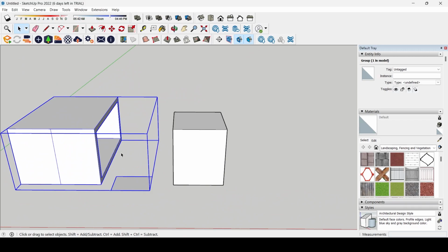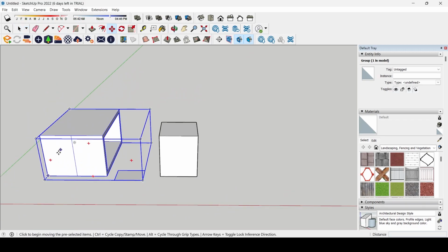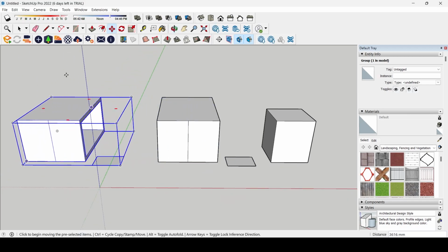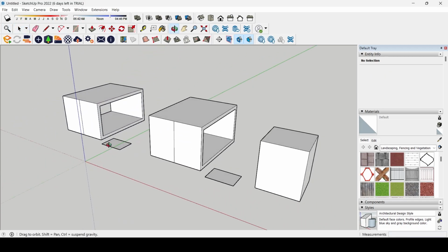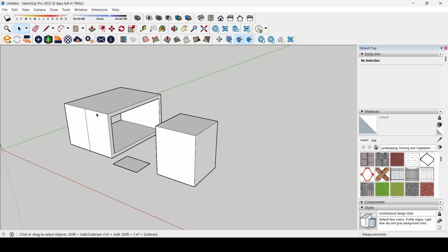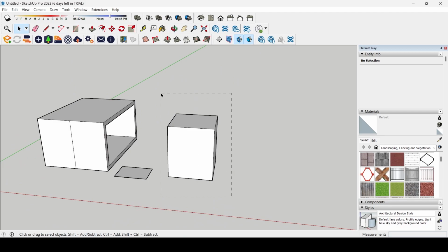And you can also see if I just take the move tool here and I press Control, you can see that on my cursor now there's a plus, and that means that we are copying it now. So if I click and drag and put it over here, you can see I made a copy now of the model. If I just delete this again, what's also nice for architectural modeling is if you have some instances that are similar to each other, you can make